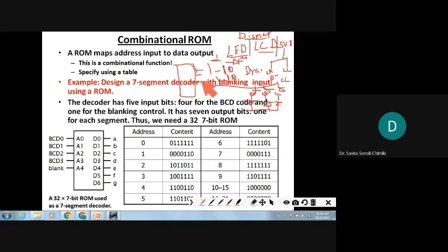For the 7 pins, one will be connected to this, another will be connected to this, another. So like this, depending on whatever data you send, 0 or 1, see here 0 1 1 1 is there. So if you send 0 and all 1s, what will happen? It will keep everything unlit, right? So what will happen? The 0 is displayed there. Only this is sent with 0, right? So like this, from the decoder you are going to send the data to control the 7 segment.